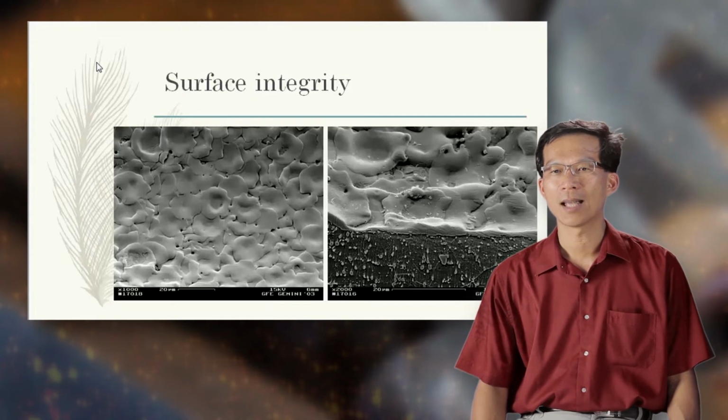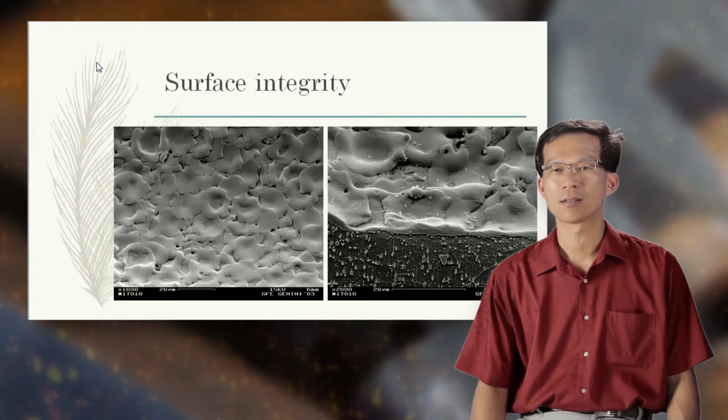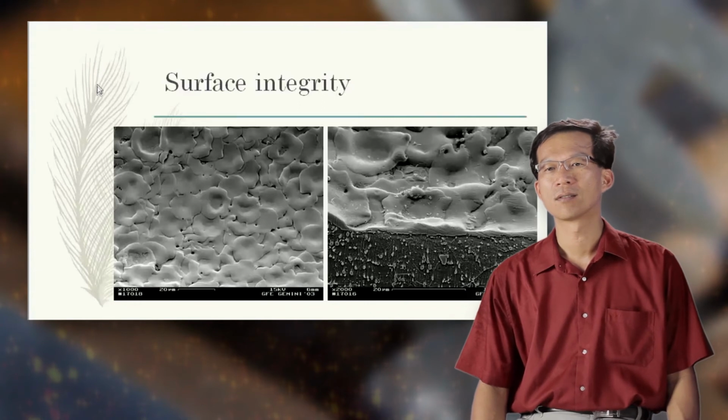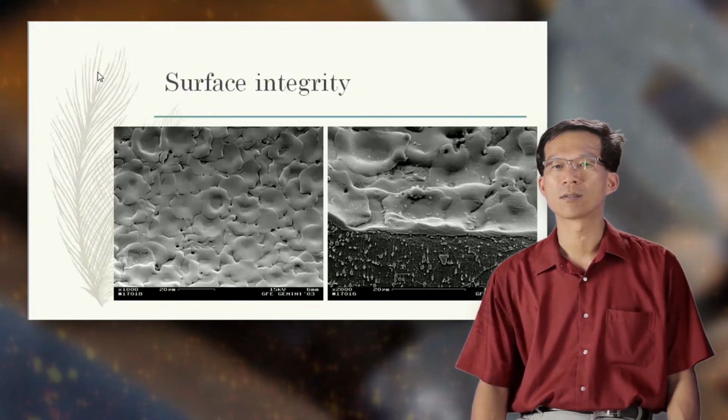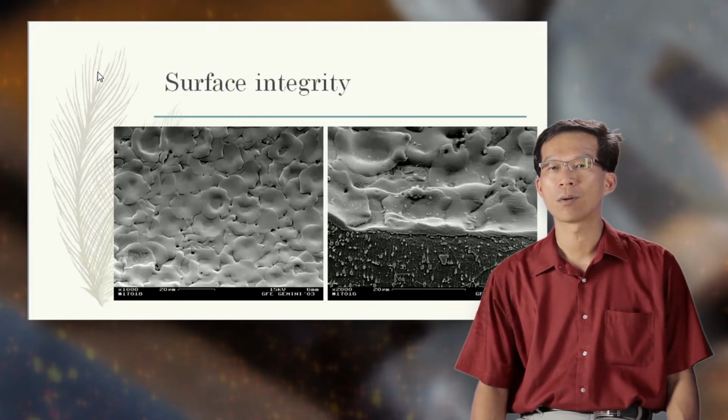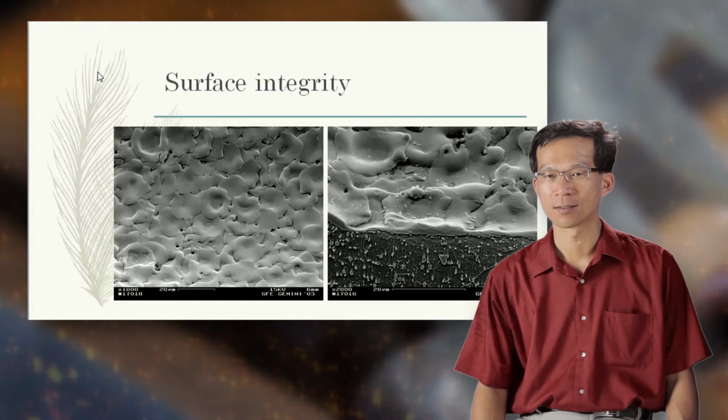Although it is beneficial in terms of enhanced abrasion and erosion resistance, the defects within it, such as voids, cracks, and induced stresses, cause an overall deterioration of the component's mechanical properties.